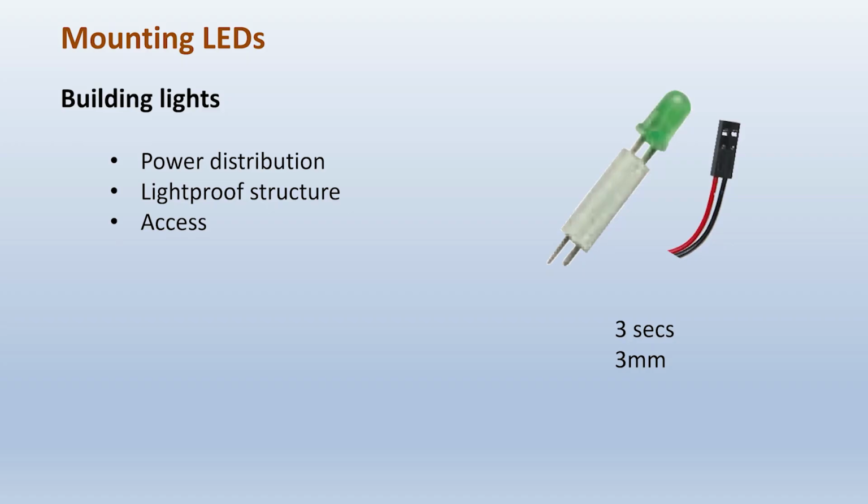If you have to solder, just to remind you of the 3-3 rule, which says you shouldn't ideally have the soldering iron on the pins for any more than 3 seconds. Otherwise, the heat might transmit up and damage the inside of the LED. And the 3mm one is, if you have to bend the legs of the LED, don't do it any closer than 3mm from the case. Otherwise, you're liable to crack and damage the case.